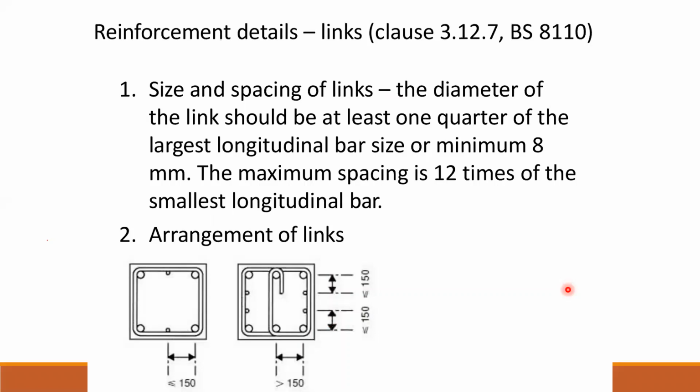Then of course, what shall we do? The 6 millimeter bar is nominal practice in Sri Lanka. Then at least you can double it and use it. It's one way of doing it. But if you are really tied up with the code, the minimum bar to be used for the link is 8 millimeter.